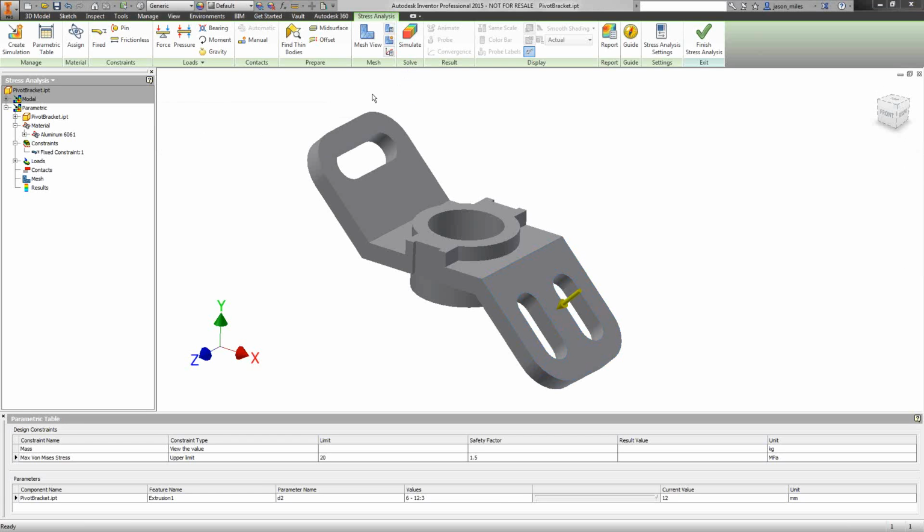So with Inventor, it actually performs an automatic HP refinement for parts. So in this case, we want to add an additional H refinement iteration. And what H refinement does, it increases the number of mesh elements in areas where the results need improvements. So maybe it might need a little bit more, maybe in this area here, and maybe on the back side